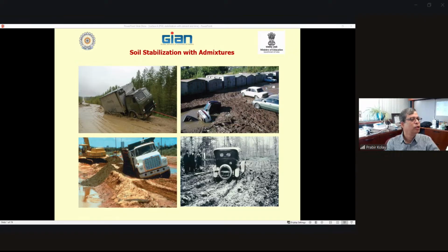So now I'm going to talk about soil stabilization. As I mentioned earlier, there are four major soil treatment methods. One is mechanical, then hydraulic modification, which is getting rid of the water, then chemical modification, and the last one is inclusions, or using geosynthetics. Today I'm just going to talk about soil stabilization with admixtures.